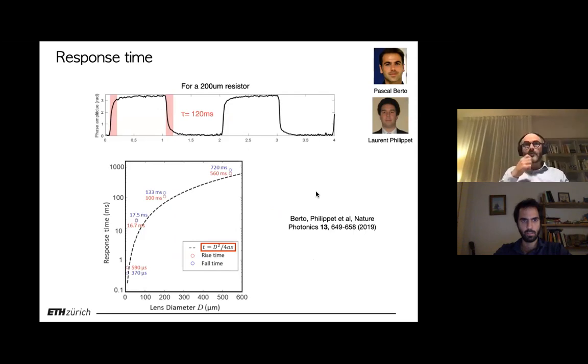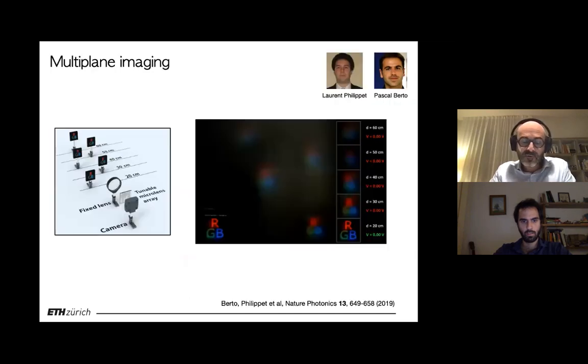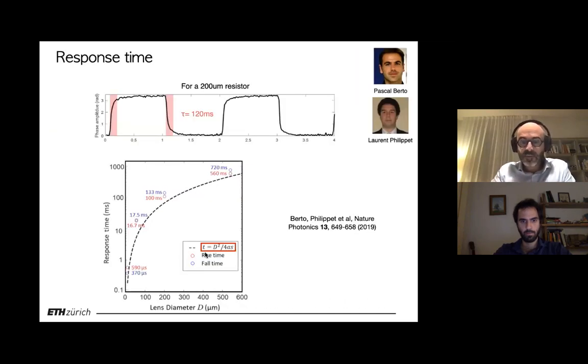So when we talk about heat, usually we think, okay, fine, but this is very slow. It's very slow because we have this experience of the kitchen, of the pan, and you heat up, and these things take a while to reach a homogeneous temperature. But in fact, there is a rule of thumb that tells you that the time it takes to heat up is determined by the square of the size of the system divided by 4 times this α, which is what is called the thermal diffusivity.